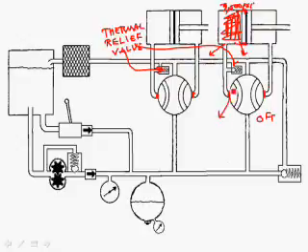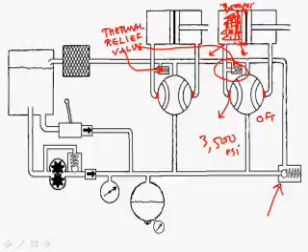So to prevent that, this thermal relief valve is down here. It's really just a miniature pressure relief valve. Works off of the same thing. It's probably going to be set to say maybe 3,500 psi. And so if the pressure in here gets too high, just one little drop of fluid is going to go past this ball, push it out of the way, and go back to the reservoir. Just one little tiny drop would be enough for this pressure to drop dramatically.